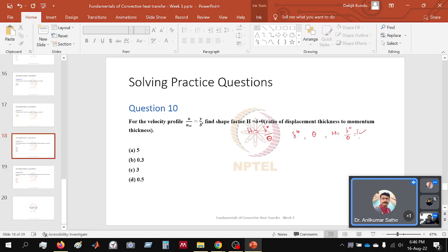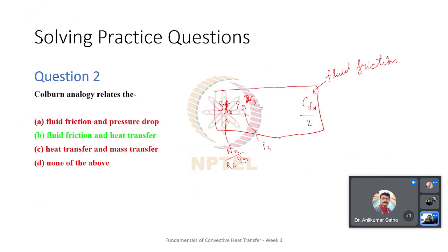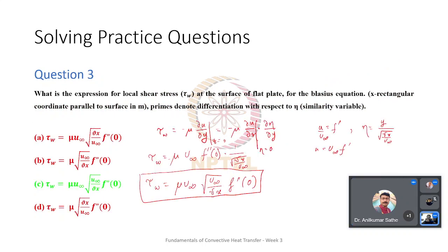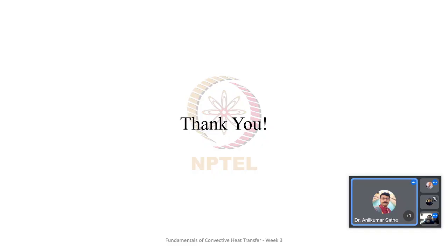Which of the following assumptions is not valid for Fourier's law of heat conduction? No heat generation, it is very straightforward, it is an assumption. Then constant thermal conductivity, that is an isotropic material, that is an assumption. And the third option, which I selected, is no time required for heat to propagate through media. And option D is none of the above. The correct answer is none of the above. I clicked on answer C, no time required for heat flux to propagate through media. So I want clarification related to it.